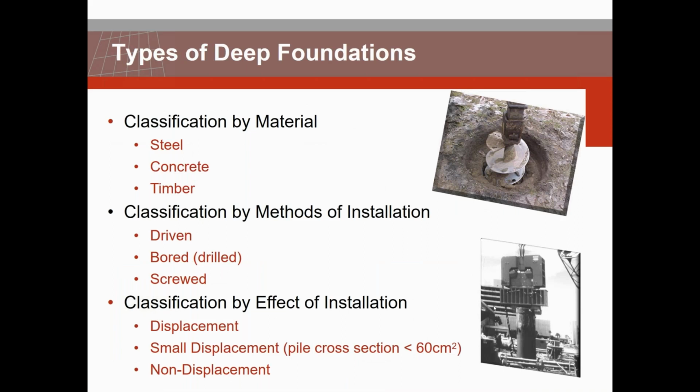Deep foundations can be classified by material, by method of installation, or by effect of installation. In terms of material classification, we have steel piles, concrete piles, which are the most commonly used, and timber piles. In terms of installation method, we have driven piles, drilled piles, and screwed piles. And regarding the effect of installation, you have the displacement piles, the small displacement piles, and the non-displacement piles.